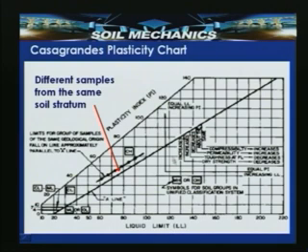So, for a liquid limit of 120%, the soil is exhibiting an increase in plasticity index. This line above the A line is the limit for a group of samples of the same geological origin, which fall on a line approximately parallel to the A line. So, different samples from the same soil stratum exhibit similar characteristics.